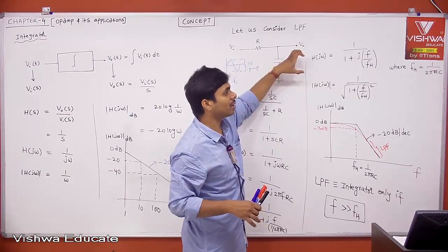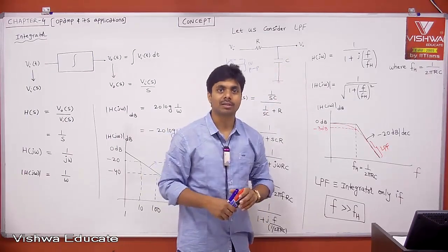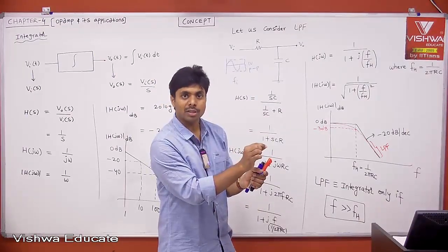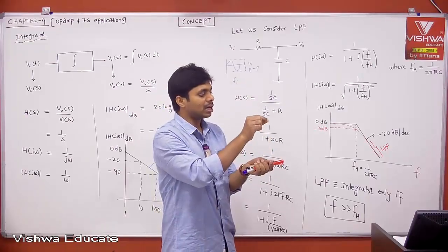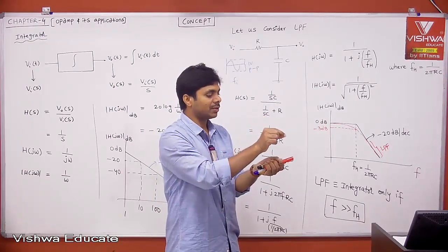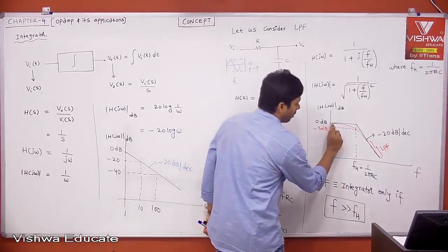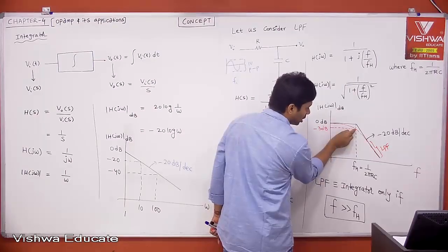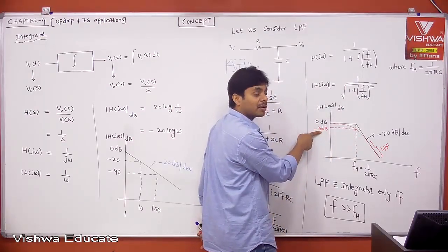Therefore, up to what power do people agree that it is acceptable? That is 50%. The maximum power you can deliver to the load at low frequency is 100%, but as the signal frequency increases at the input, that 100% becomes 80%, 70%, 60%, 50%. The power delivered to the load keeps decreasing up to this point, which is minus 3 dB, the 3 dB point or half power point.